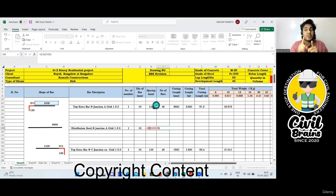You're finding the number of bar, so you need to do plus 1. So plus 1. Finish. You'll get 12 number of bar. Got it? But you have to do round up. I always tell you, whenever you're doing number of bar, you should always say plus 1 dash comma 0. Close the bracket. Hit enter. 12 number you'll get. Okay.